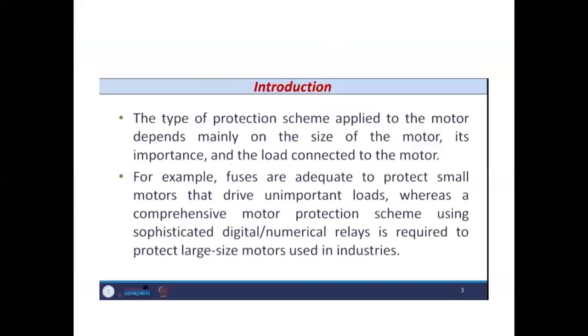The first factor is the size of the induction motor. The second is the importance of the induction motor, and third is the load connected to the induction motor. For example, fuses are adequate to protect small motors that are used to drive some unimportant loads, say, for household applications.